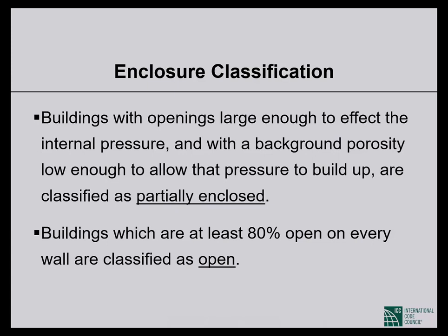Partially enclosed. A partially enclosed building has windward openings. It has suction openings, but the windward openings predominate. So more wind comes in than can get out, so internal pressure builds up. That is a partially enclosed building. Okay, one more time.